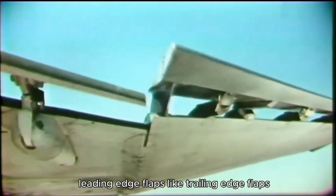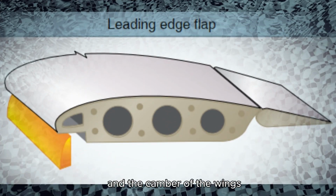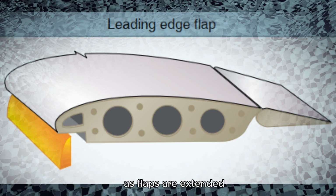Leading edge flaps, like trailing edge flaps, are used to increase both coefficient of lift and the camber of the wings. A small increment of leading edge flaps increases lift to a much greater extent than drag. As flaps are extended, drag increases at a greater rate than lift.